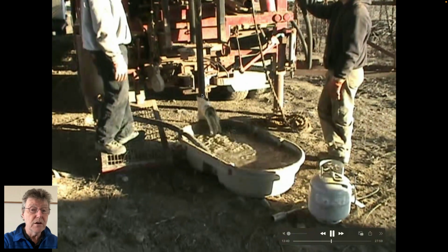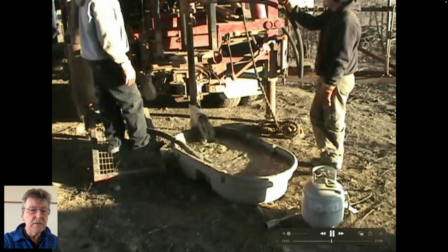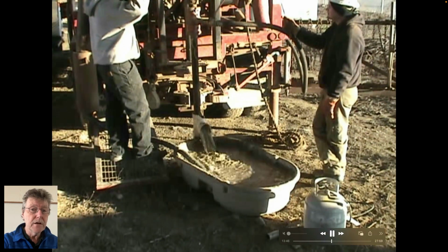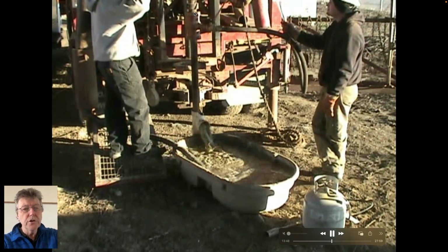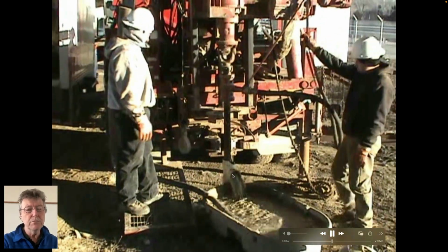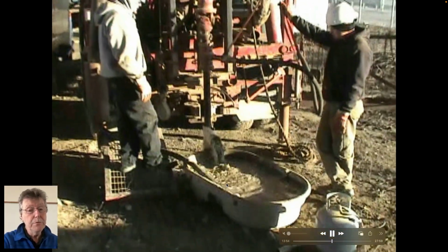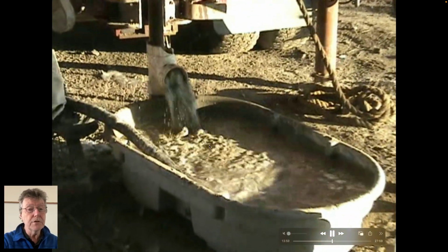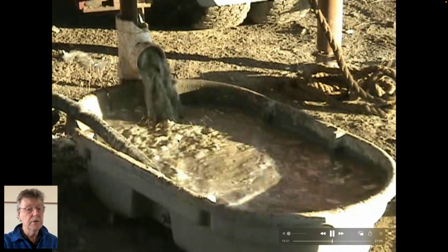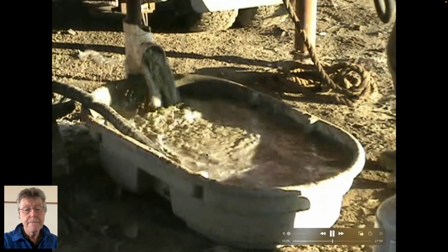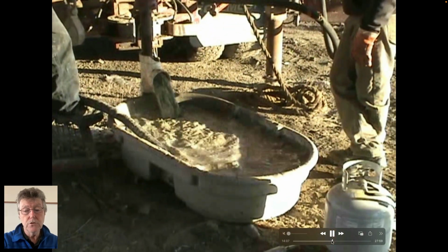So this is the drill going down, water going down inside the drill string from this supply pipe. A turntable and a universal joint go down to the bottom of the hole, and it brings up the cuttings. So this would be circulating water, maybe with drill mud, but also with cuttings in it. You might put a sieve across here to sample the cuttings and see what you're going through. Pretty rudimentary. So that's drilling.